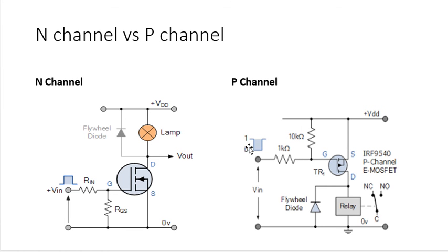So when this negative signal is not there, this positive signal immediately becomes more prominent and the MOSFET will immediately get turned off. If you do not provide this resistor, then this MOSFET may or may not get turned off. We can't guarantee, because it has some charges, and it may also get falsely triggered. So to prevent that also, you can provide this resistor.